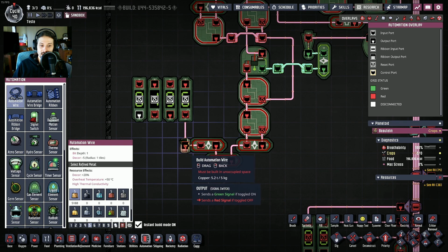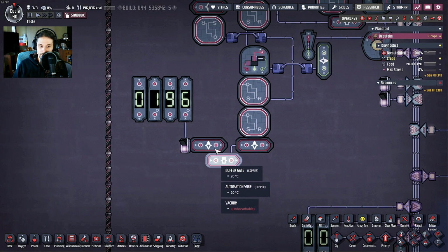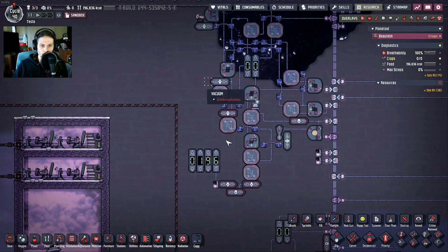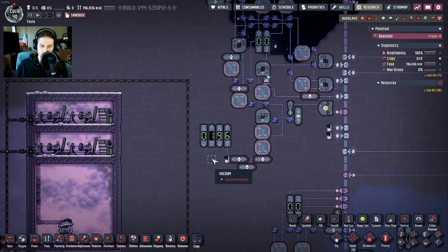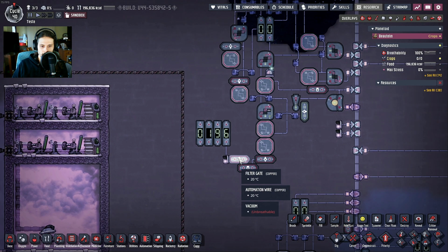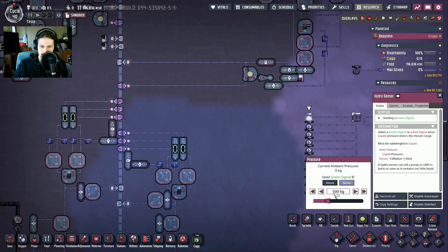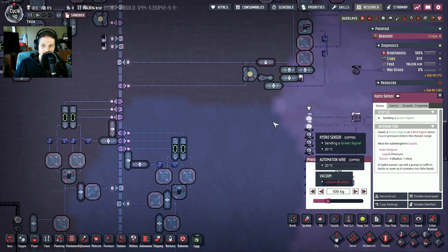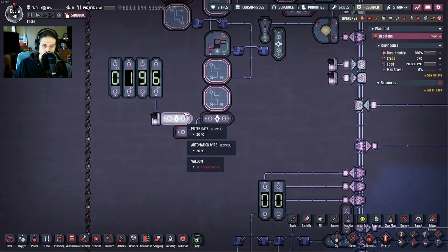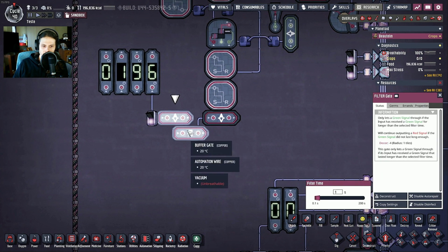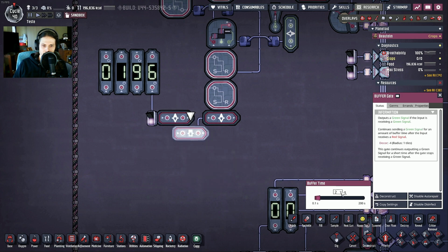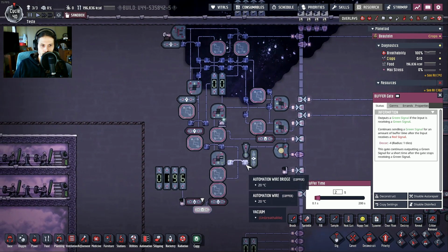The green signal starts over here, and in here we have our very first safety system. You see, the encoder unit cannot handle flickering, your sensor going on and off, on and off all the time, because it's right there in the threshold. Let's say an Atmos sensor, one of these. The fluid is 499, 500, 499, so it's constantly flickering. We can't have that. That is going to send the system into haywire. That's why we have this, to prevent flickering. Flickering gets filtered through here, and the buffer guarantees a stable signal for at least 2 seconds, which is more than enough time to make the encoder unit do its thing.